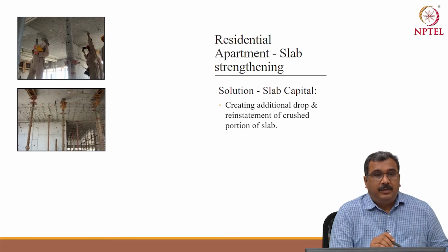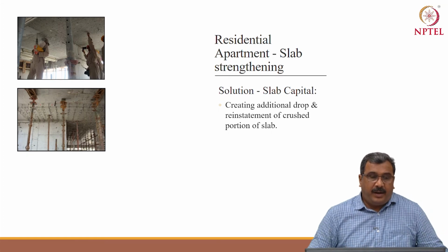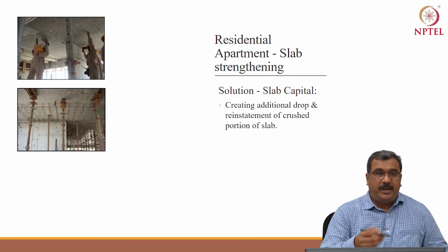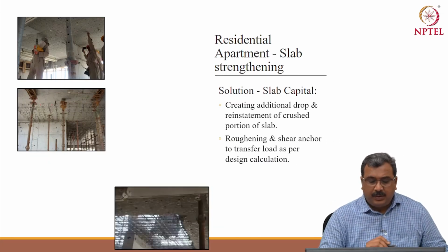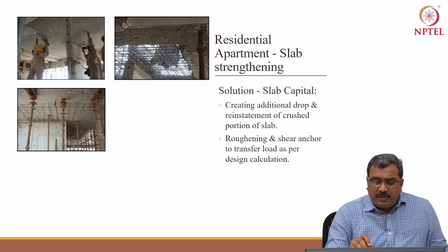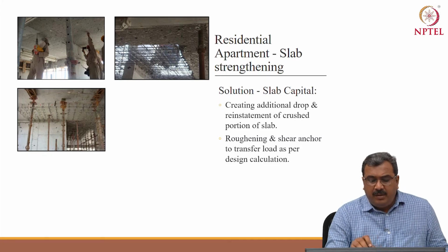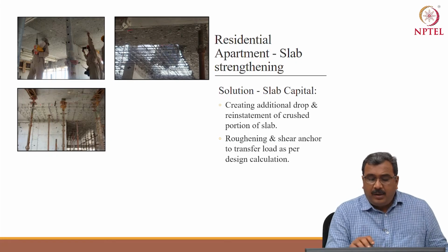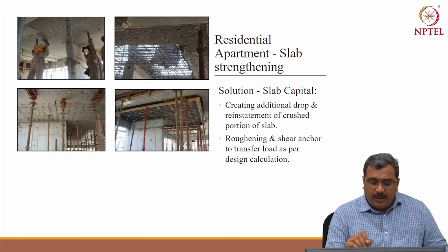Vs, Vc, friction coefficient, everything has been considered, and then what shear force it's going to transfer has been designed. The portion which was distressed crust has been removed after proper supports. The outer part was also roughened. New reinforcement has been tied.